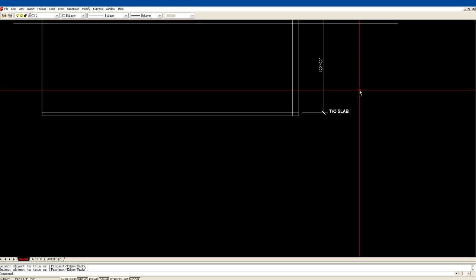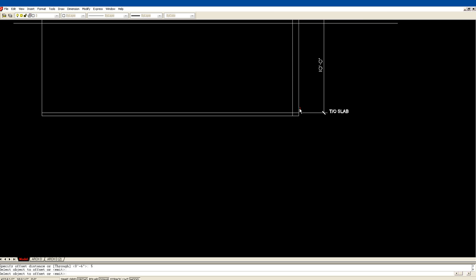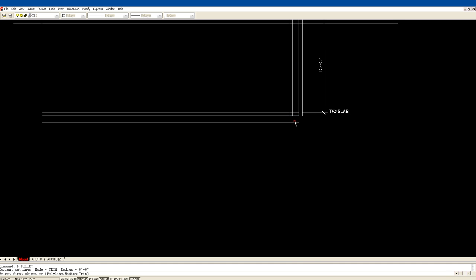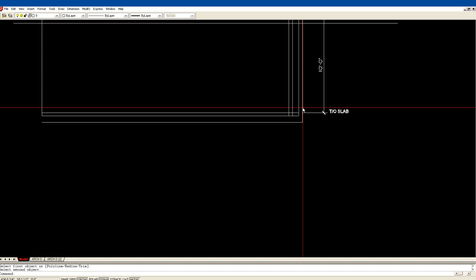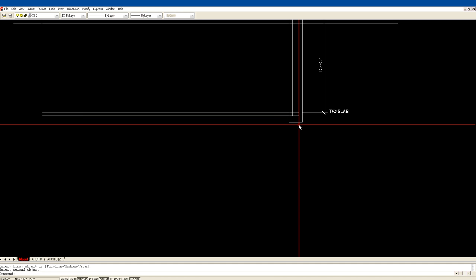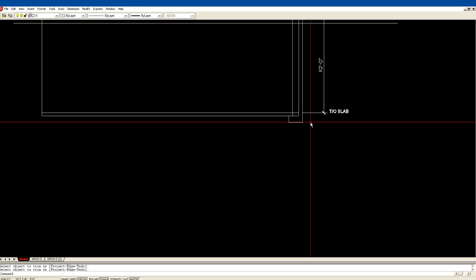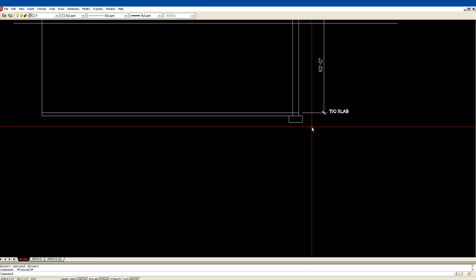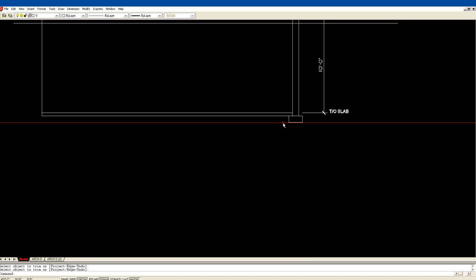And so if it's 18 inches minus 8, that leaves you 10, divided in half is 5, so offset 5 inches from there to there and there to there. And we just said it was 8 inches thick, so offset 8 inches, and just join these guys up. I'm just going to fillet that to that, and that to that, and I'm going to trim that to that, and I second fillet. Okay, and I'm going to trim that to that. Okay, so that's how this all works.